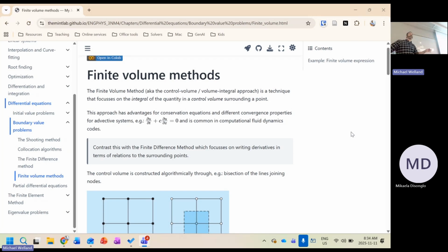You go here, you apply your finite difference formulae, and you get, okay, this is delta t, you have delta t over here. You do all your delta t's, and then generally you would also do some kind of divergence of that, right? And the way that you would roll that divergence in just depends on how you're applying your finite difference. If k, by the way, if k is also dependent on t, technically you need to do finite difference on this guy. This is your quantity that you're doing the difference on, right? Not just your temperature, because that's also the dependence in there.